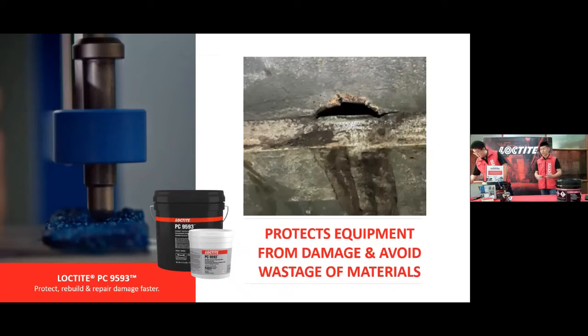Okay, I got this photo in the slide. It's a very good example. This is actually solid hoppers. So along the time, the solid minerals continue to impact on these bunkers, and because these bunkers have no specialized protective layers on the metal parts, the impact continues and causes through holes, and the minerals inside flow out and cause a mess in these processing plants. So that's the reason why we need these protective coatings, so that we can protect our equipment to avoid this kind of issue happening in your plant itself.